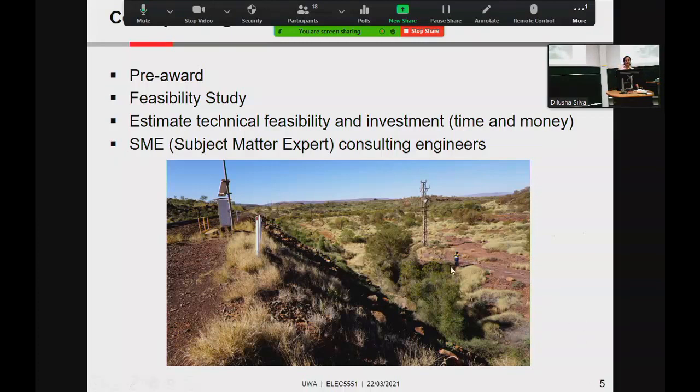He's standing here. This is the closest we can get for a fiber. So this is just an example of why we need feasibility. We need to get to this cabinet. We can dig a trench, put in bedding and pipe, or we could buy an outdoor rated cable and just bury it directly. We could do something called above ground troughing, like a concrete channel. So all these options. This photo just tells you all the different little aspects we look at during concept design.